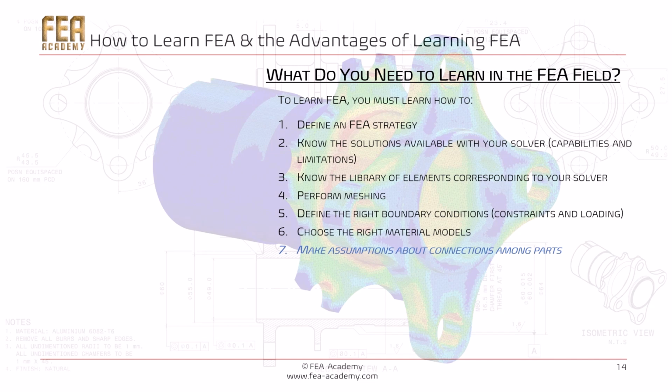Also, you will have to make assumptions about the connections among parts. Because most of the time, we use finite element analysis in order to solve complex problems. And in these complex problems, we have different components in the simulation. And these components, these parts, they are connected together by bonding, by fasteners, by different technologies. So you will have to learn how to model these connections.